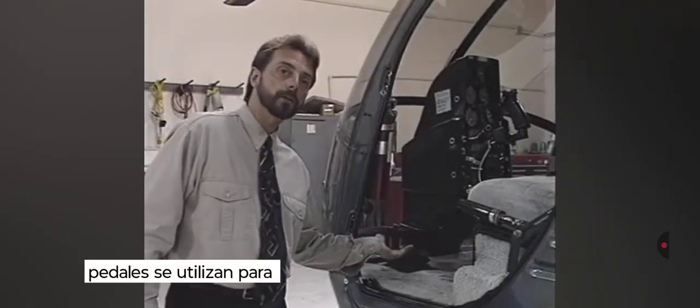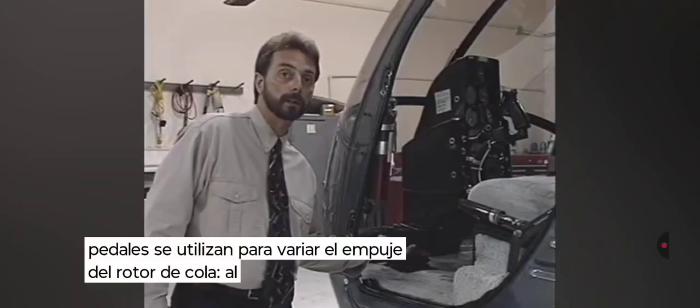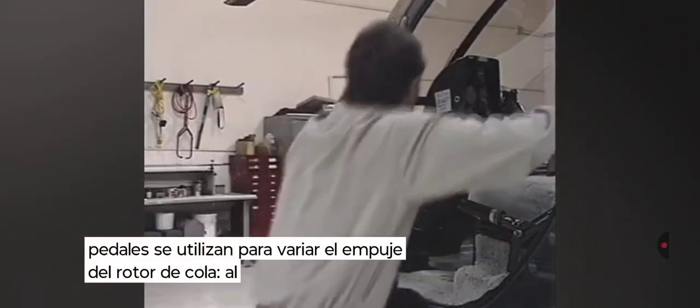Foot pedals are used to vary the thrust of the tail rotor. Pushing left pedal increases the thrust of the tail rotor to the right, turning the helicopter left, and vice versa.